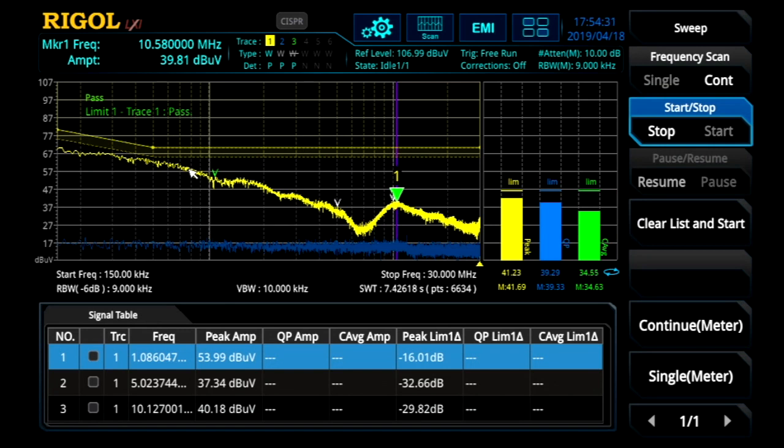And then as we get higher, right around 10.5 megahertz is the main peak at number 1 there. That's the switching frequency of the switching power supply. So we can see what emissions are being caused there. So this is another way to look at how much power is coming off of our switching power supply, both with a load and emulating it with a power supply. So a great kind of two-phase test to isolate any conducted emissions related to a switching power supply.